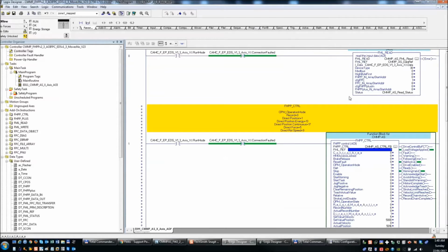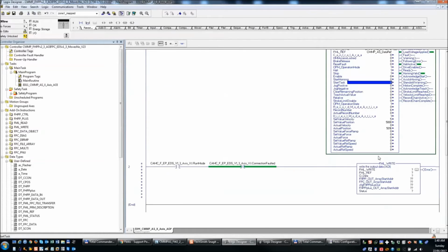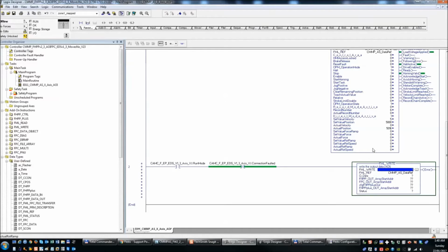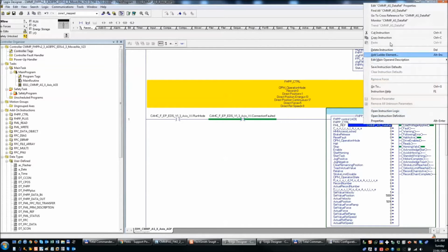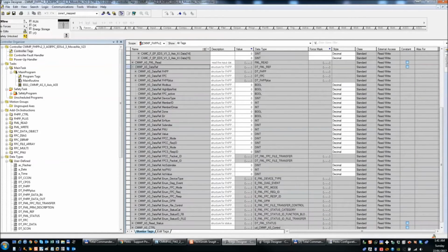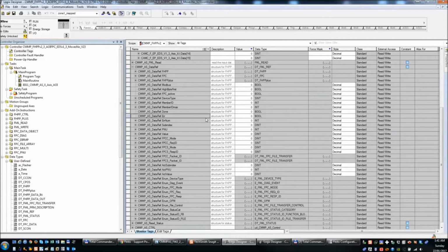And this ref here, the FML ref, that's the same for every function block. So I'm going to copy this, paste it in there, go down to this one down here, paste it in there, because this data ref is what's transferring the data from reading and writing into variables which are passed between these function blocks. So the common data structure that communicates from tags in the project to the real I/O is in fact this one data reference here. So if you go to monitor this, expand it, you'll see here that you have all these tags in and out, and then you've got a bunch of other things that are part of the data structure.